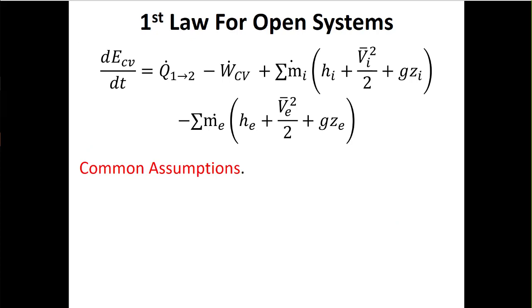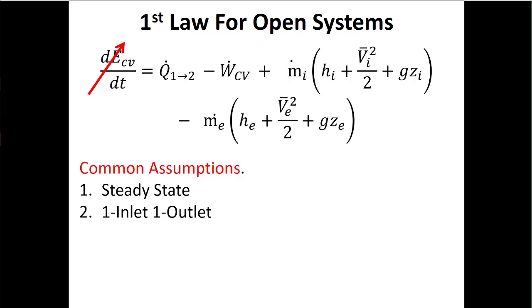So the way we're going to do this is we're going to run a first law analysis, right? Because now we want to find what's going on with that thermal efficiency. So we're going to run a first law analysis on all of the different components. And because every process is an open process, we're going to use the open version of the first law, right? We'll say this is at steady state, one inlet and one outlet for all of these components.